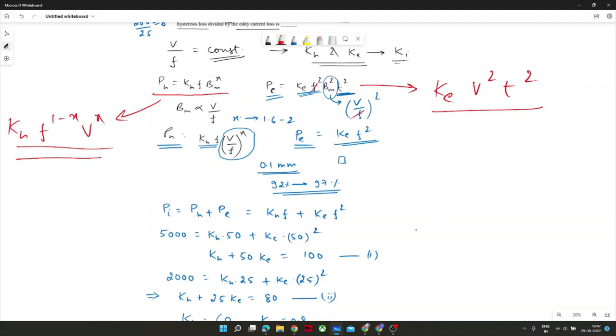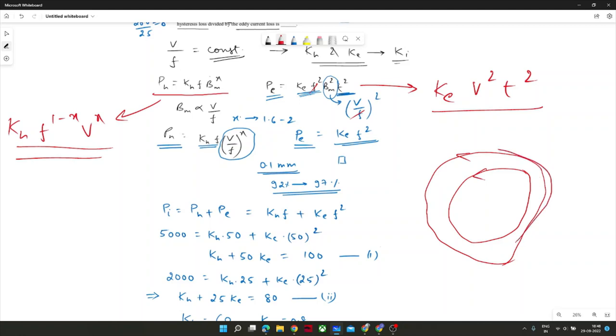I showed you in my earlier lectures that to complete one pole in any motor, the flux will flow like this. This is radial direction, right? It is going from one north pole and coming to south pole. If there is no resistance in this section, this axial, some portion of flux would leak to axial and some losses would correspond to that axial component.